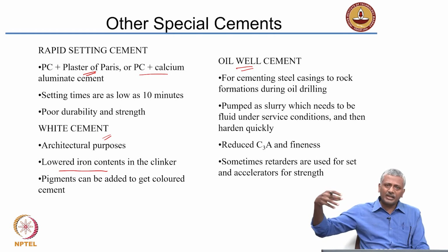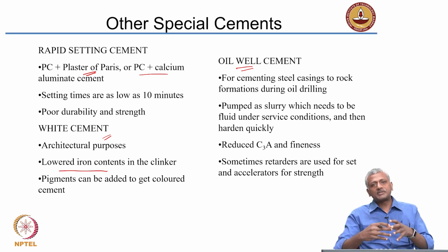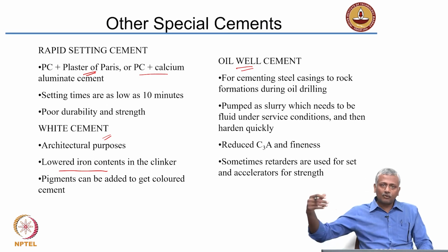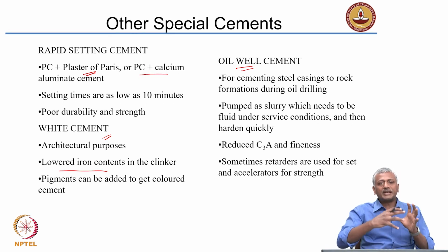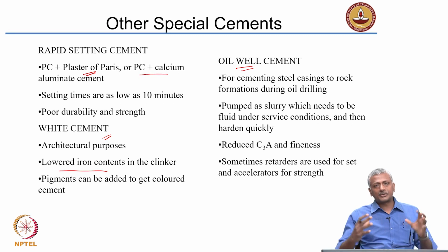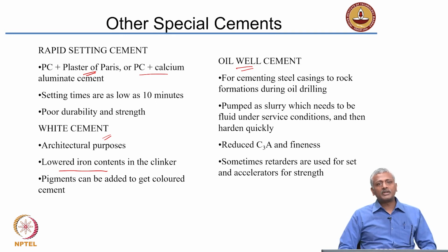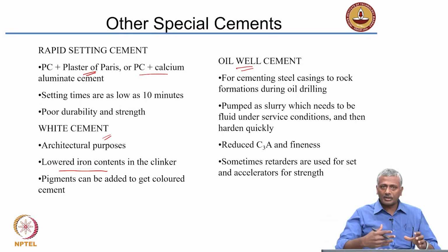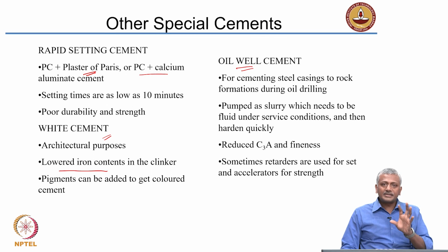When you drill very long bores into the rock to extract oil, to prevent the soil from collapsing, you need to line the walls of the bore that you have dug with cement, and the cement should be such that it can flow very long distances after mixing, but at the same time when it comes to rest, it should form a layer on the soil surface so that the soil does not cave in. So, it is a very uniquely formulated cement, and it needs to have a combination of different types of additives to ensure that it is flowable for a long time, but when it comes to rest, it sets and hardens almost immediately. So again, this is something that needs to be formulated very carefully.